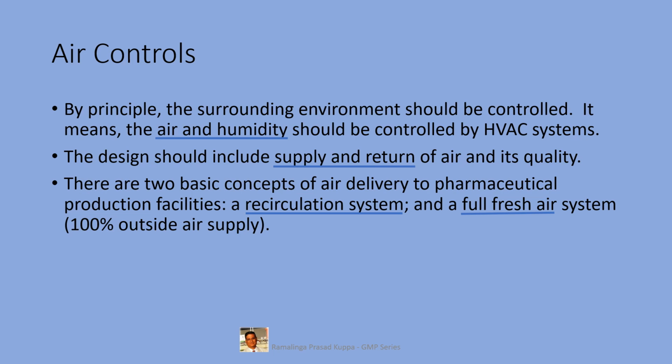Mostly a recirculated system is used when the temperature and humidity inside the closed room is very important to control. Also, it saves a lot of electrical energy. Also, when the product is very potent and highly sensitive in very low dosages, and if it is vented out, the environment gets contaminated. There could be other reasons also for selection of a particular type of system. The risk assessment should provide necessary supporting data for all these things.